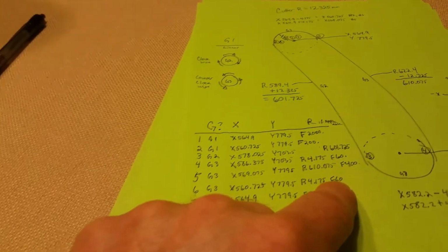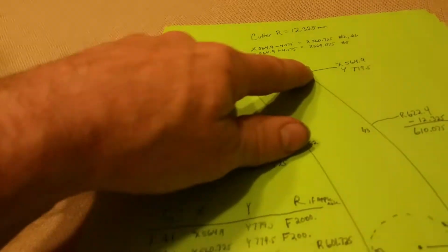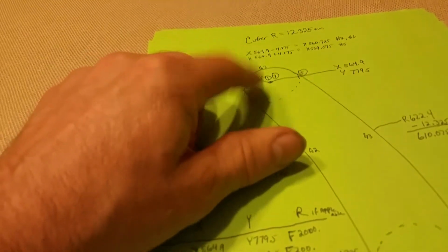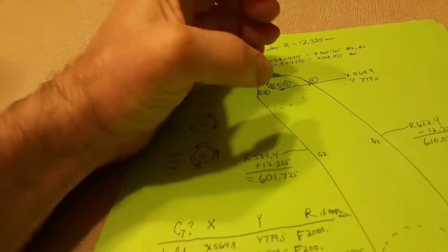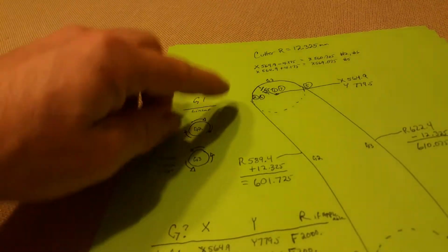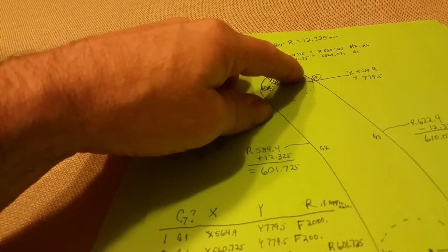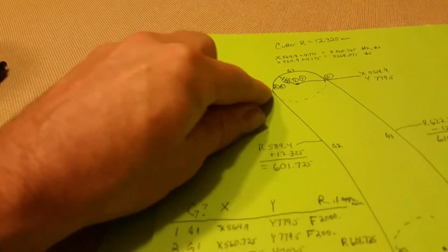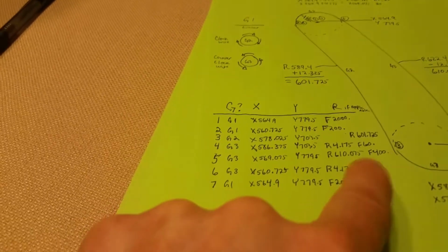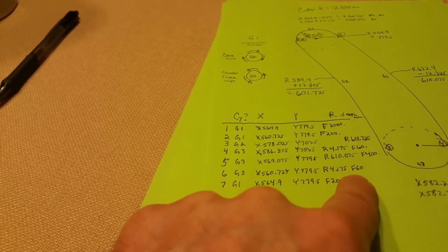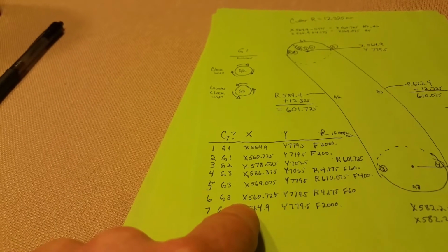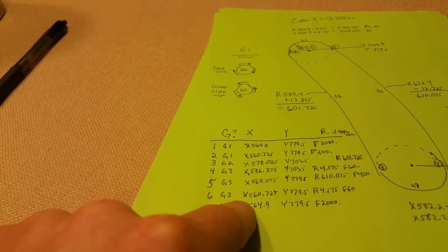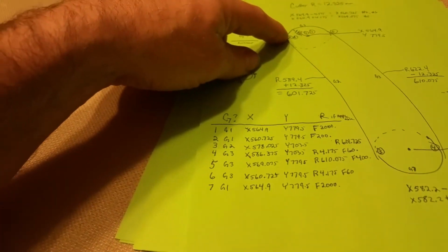6. Got the feed rate cut down. Feed rate would be significantly higher if the drill I used was the same size as the end of this slot, but it isn't, so this actually moves along pretty fast getting to this side of the slot. So I've got that back down to a feed rate of 60 millimeters per minute. So there we are on 6, which is almost the end of the slot. It's finishing up its cut at the 9 o'clock position.